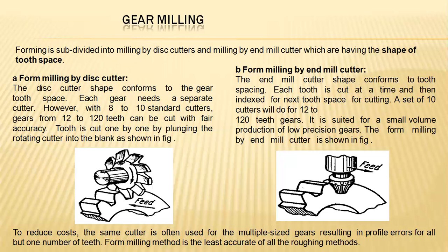Coming to the disc cutter, the disc cutter shape conforms to the gear tooth space, and for each gear size, it needs a separate cutter.